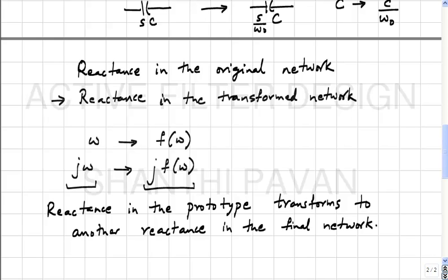So the inductor in the original network has transformed into another box whose impedance is purely imaginary. Similarly, a capacitance is transformed into another box whose impedance or admittance is also purely imaginary. If your impedance or admittance is purely imaginary and physically realizable using lumped elements, then it must be made of a combination of inductors and capacitors. Is this clear?